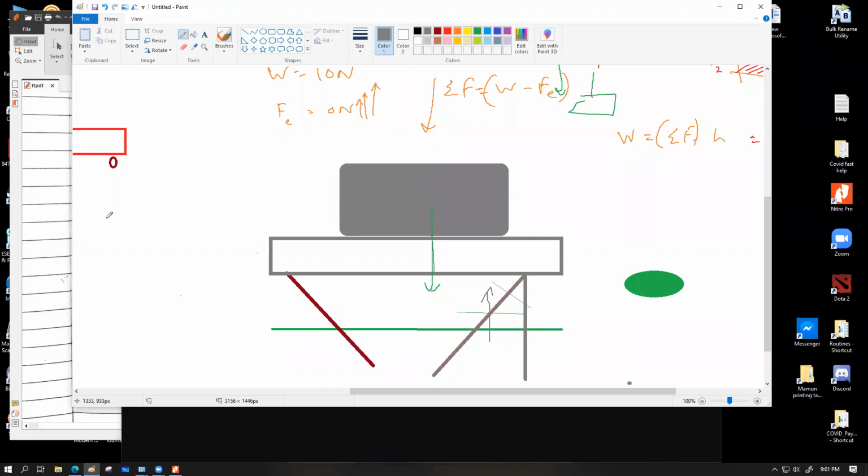So what happens is that whenever you are applying the force with a really sharp scissor, you're producing a very large shear stress, which is separating out those molecules from one layer to another layer. Something like this. Let me show you an example which might make better sense. Let's say this is an object, red. Let me fill this up. Shear stress would try to disintegrate the object in this manner. That's exactly what happens when you cut something. Whereas longitudinal stress is going to try to separate the object like this.